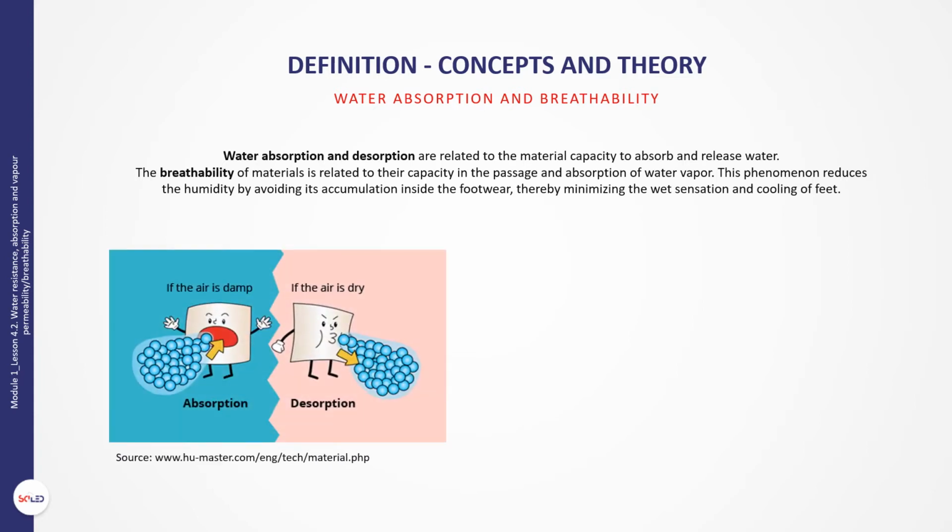The breathability of materials is related to their capacity in the passage and absorption of water vapor. This phenomenon reduces the humidity by avoiding its accumulation inside the footwear, thereby minimizing the wet sensation and cooling of feet. The accumulation of humidity in materials can also reduce their thermal insulation, because water is a much better thermal conductor when compared with air.